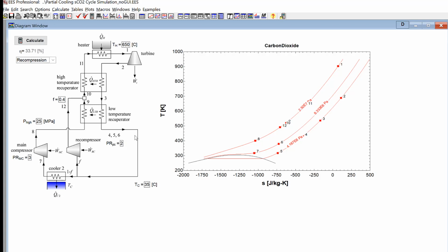It doesn't actually change the simulation, so the next thing I've got to do is think about how I would change the simulation, basically to remove the precompressor and the cooler. So if I want to remove the precompressor, basically what I need to do is just set the pressure ratio of the precompressor to 1. And I'd also like to hide this input.